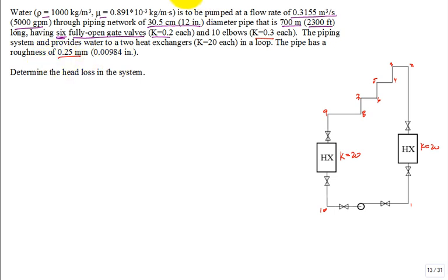This is a very common configuration on, let's say, this campus. We have a chiller somewhere. Okay, well, what's the chiller do? Produces cold water, brings in warm water, and puts out cold water, chilled water. And so there's some heat transfer out of the fluid. Then it's pumped over to a building, let's say this building right here, and we have airflow that goes over another heat exchanger, and that airflow then is cooled, the air is cooled, and so there's heat into the fluid. So Q dot into the fluid, Q dot out of the fluid, and the water goes in a loop.